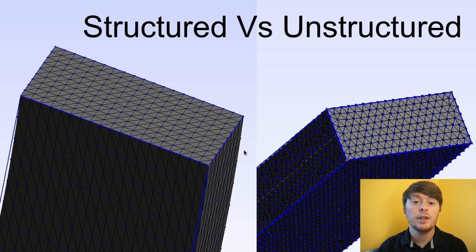But again, anything we do here, and the same with all computational fluid dynamic problems, the parameters in the mesh we put in will ultimately affect the dynamics we pull out of the system. So I put this in as just here's how to do a structured mesh, but you're more than able to get the similar dynamics using an unstructured mesh.